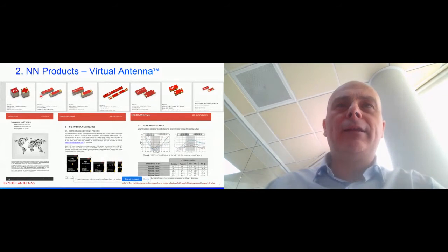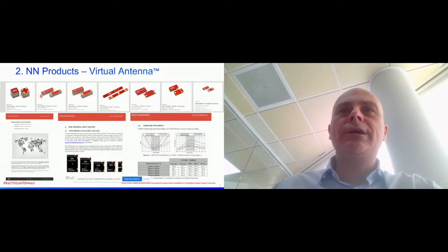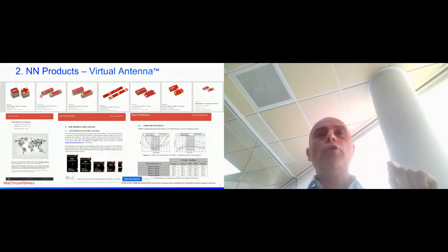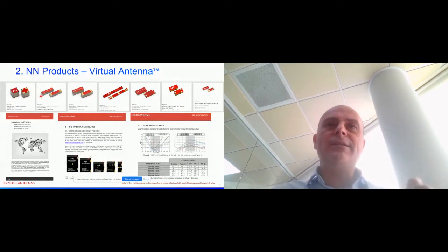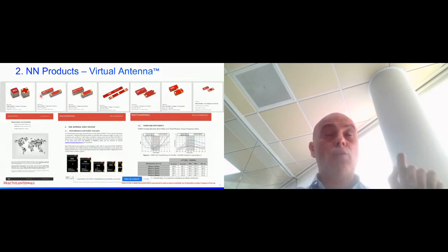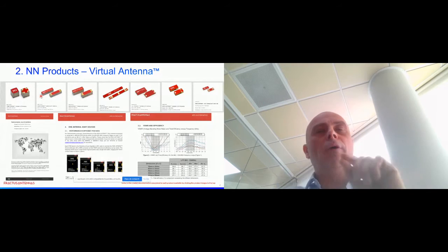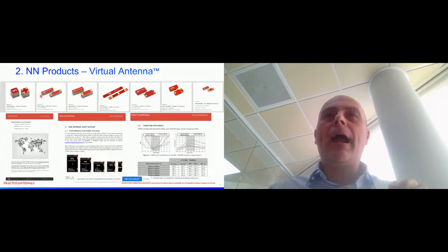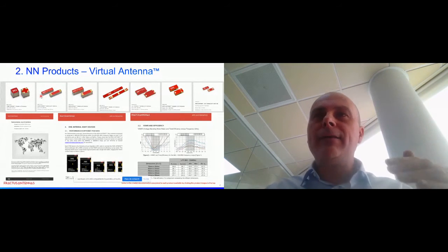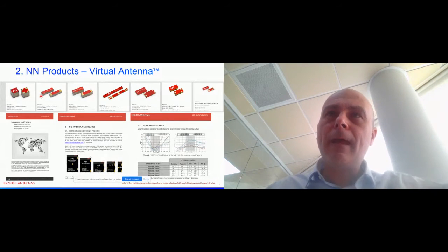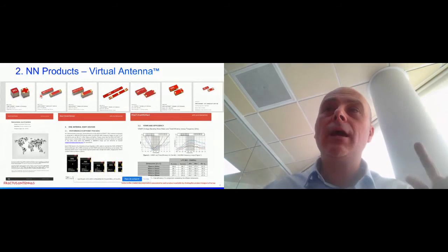Also, we have very attractive antenna boosters, the Trio MX10 and the Duo MX10, which are multi-radio antennas. For instance, the Trio can operate at the same time at 3 radios, as we are going to see now. The Duo, pretty small, is 7 by 3 by 2 high only, without clearance on the PCB, and can operate simultaneously at GNSS satellite frequencies, GPS, Beidou, GLONASS, plus Bluetooth in a single component.